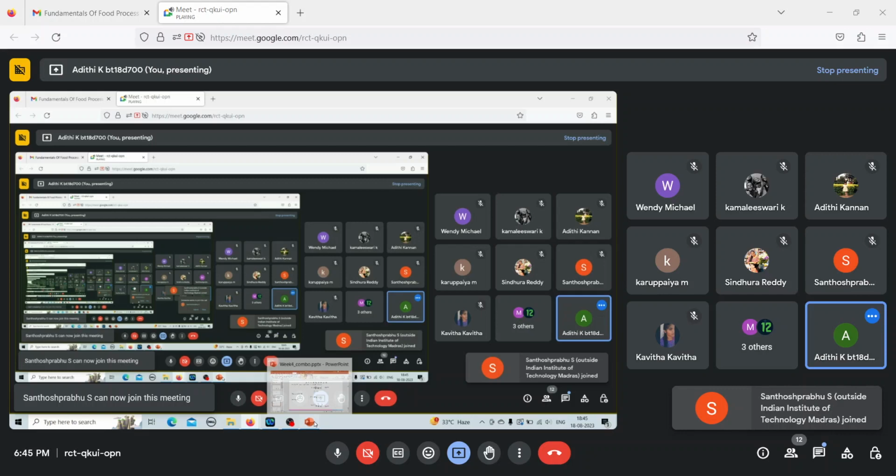Let's say I am giving steam here, and there's a process of evaporation, and you have vapor here. This temperature and this temperature will obviously not be the same. Had it been the same, you would have no heat transfer at all. If you remember, Q is equal to UA into delta T. The delta T is steam temperature minus T1, and your vapor temperature is also T1. So unless you have this difference, you will have no heat transfer. So always in the first effect, the steam temperature Ts will be greater than T1, which is the temperature of your vapor.